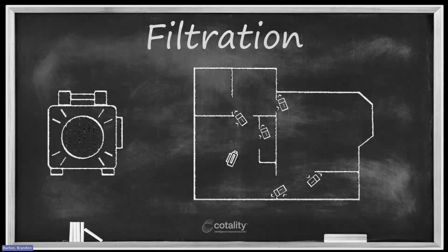Thank you, Darren. If you're now moving to air filtration devices that are being installed during the active drying process, now the strategy significantly changes. If I am using air filtration because I'm following that recommendation, for the installation of an air filtration device because cleaning alone wasn't effective, I have immune compromised individuals, and that's the reason why I'm installing it during the drying process. At that point, your air movement should be handling the circulation for you.